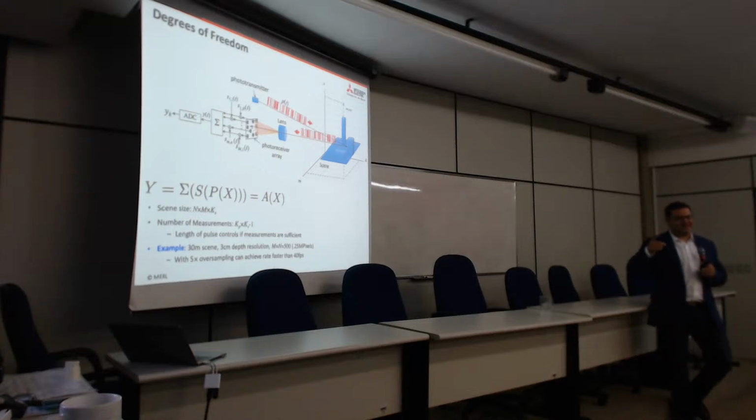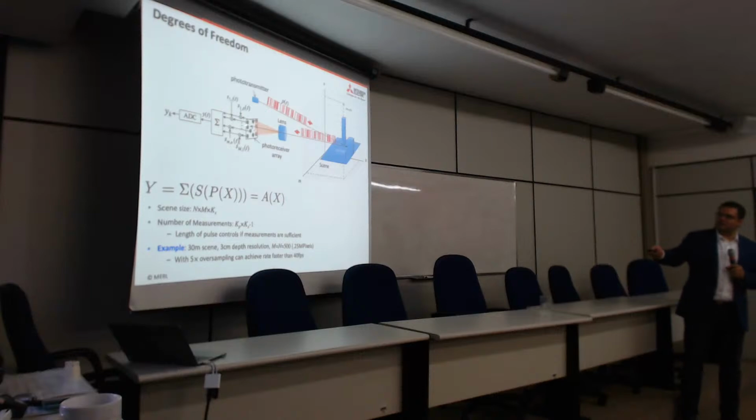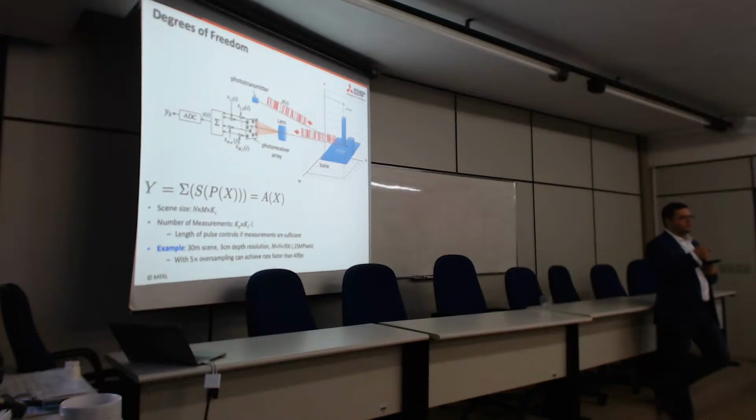It's like, oh, that's what I'm doing. I've shown this. So if you want to look at the hardware, your photodiode needs to be able to respond at the timing that has to do with whatever depth resolution you have. So you think about light traveling at a foot per nanosecond.